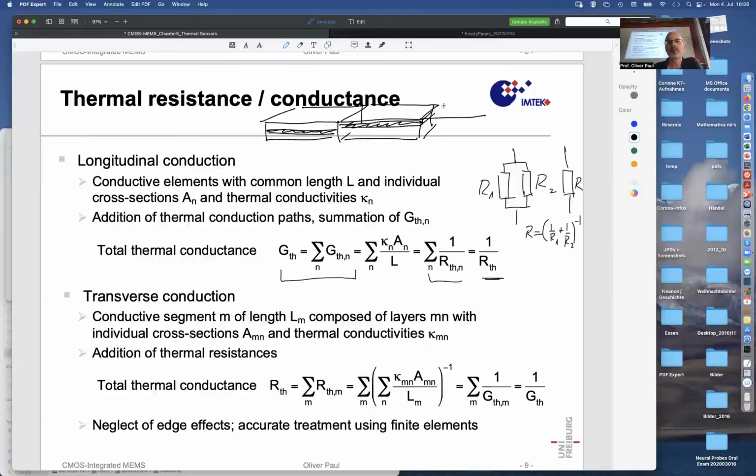And then maybe we have another piece of material that has nothing in between, just pure oxides. Then calculating the thermal resistance from here to here is like adding resistances to each other. The resistances R1, R2, and R3 can be added up into the total thermal resistance,